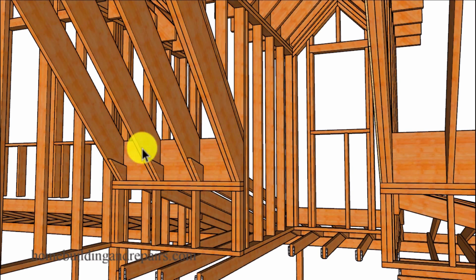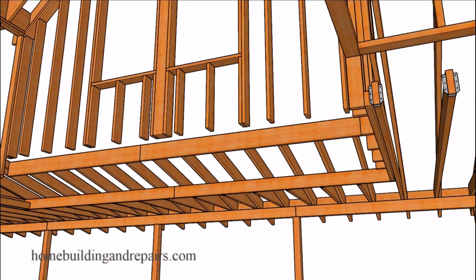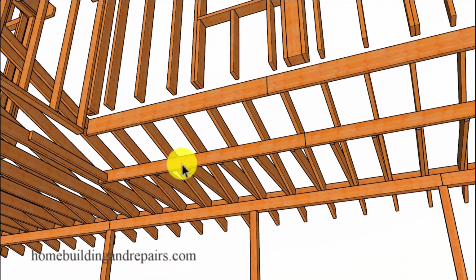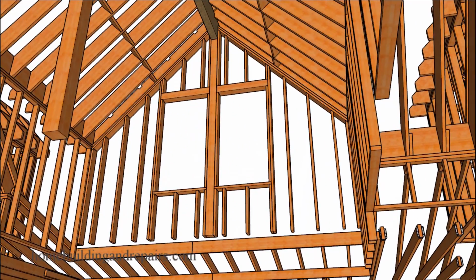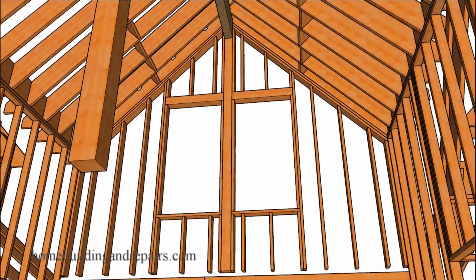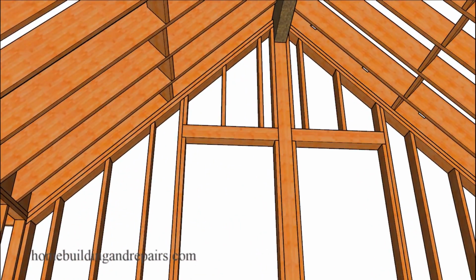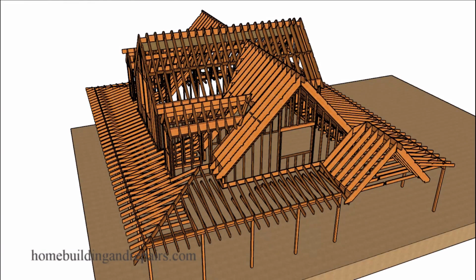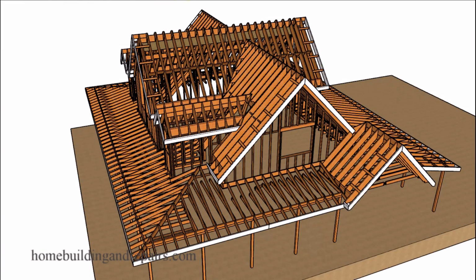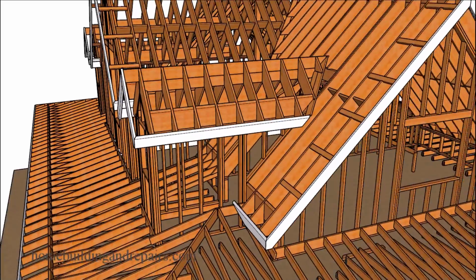Another view of the lower connection there for the rafters. A view of the porch framing here. Ceiling joist here, right here, and then our porch rafters here going up to the ledger. Ledger is going to attach to the wall framing. A view of our double windows there. And I'm sure I drew my ceiling backing in there somewhere. It just disappeared.